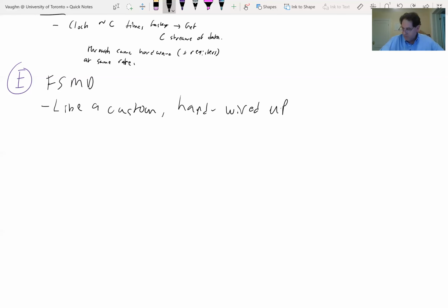Well, like a microprocessor, it's got a reusable data path. So let's say that I have computations where I need both multiply and add. Okay, so I build a multiplier and I build an adder in my hardware. But I want to reuse them. I'm going to do more complicated computations by building up results a little bit at a time, essentially in temporary registers, so much like a processor. Okay, so how am I going to do that?